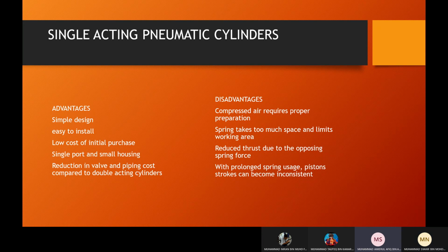So the disadvantages of the single acting pneumatic cylinder are that compressed air requires proper preparation, and the spring takes too much space and limits the working area, and it can reduce thrust due to the opposing spring force. With prolonged spring usage, the piston stroke can become inconsistent.